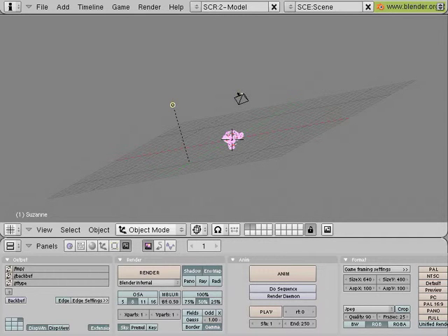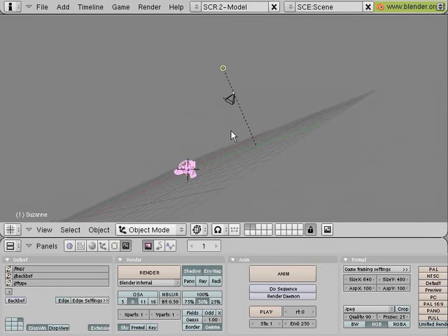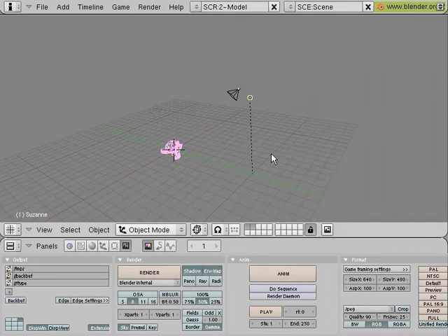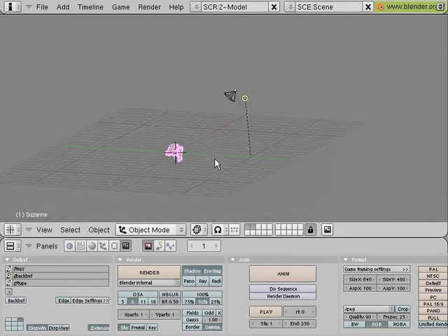Now we can also switch perspective in the 3D viewport. To switch between perspective and orthographic projection, press the 5 key on the numeric keypad. Okay, if you do not know the difference, you should be able to see it immediately. Since our eye is used to seeing objects that are farther away appear to be smaller, orthographic view might appear strange at first, which is what this is.